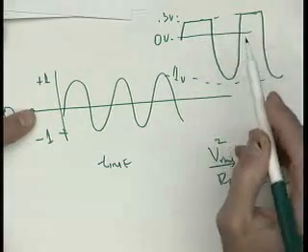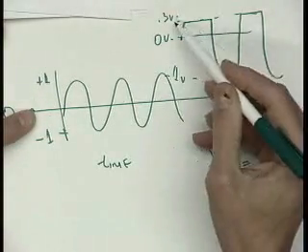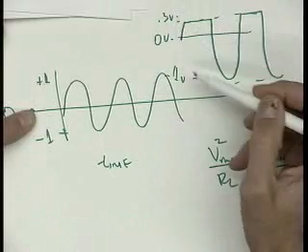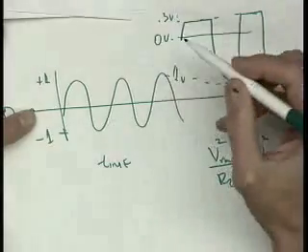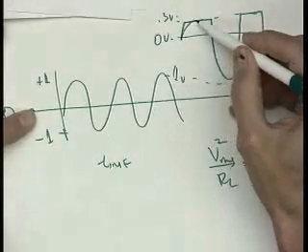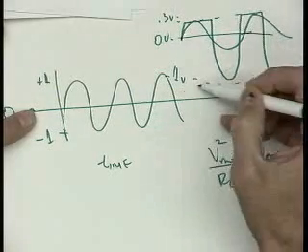Well, we say that's not acceptable, okay? If you had this situation where you had +0.3 and -1 as the limiting points, the maximum output swing you could get would be 0.3 volts, no matter what the negative side is.